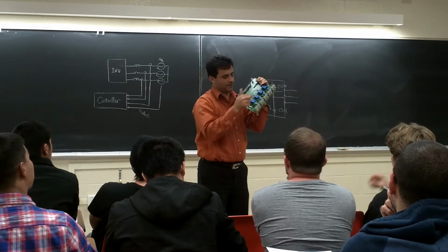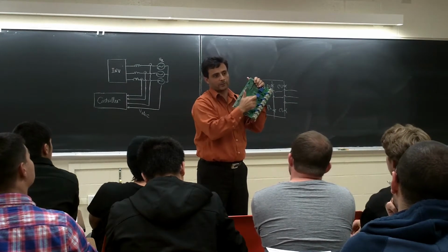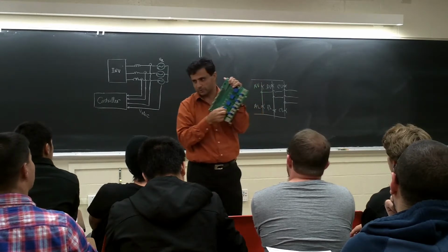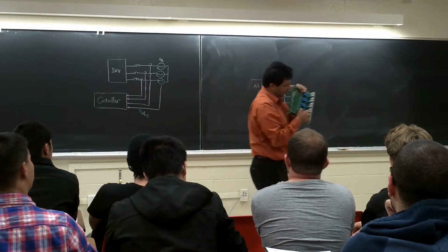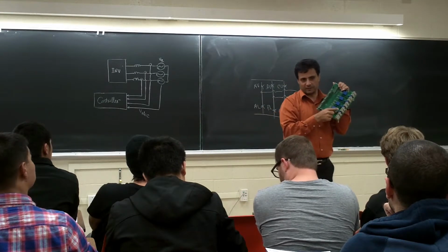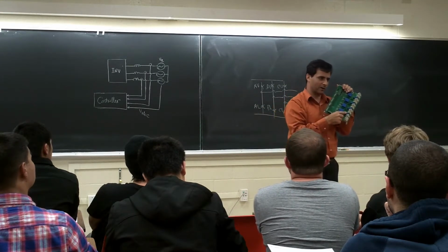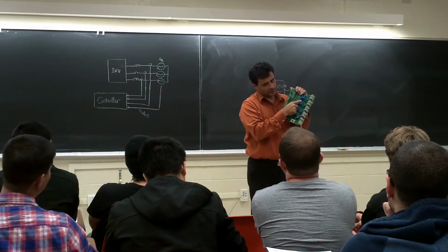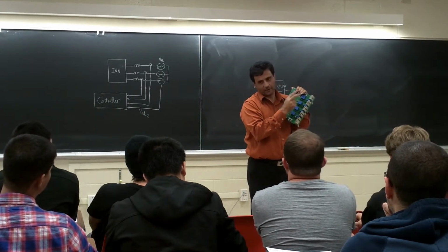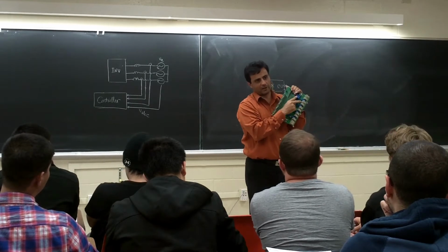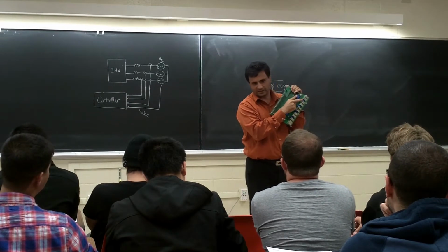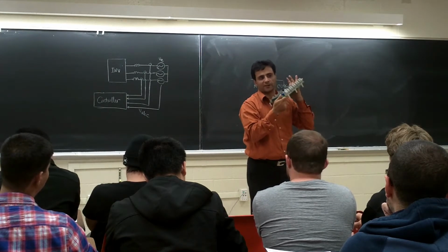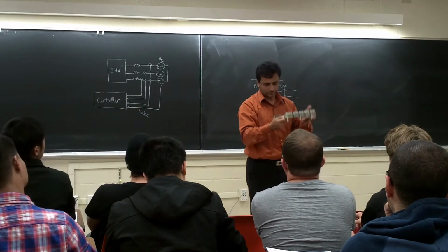Here, the same thing, and these are voltage sensors. These are again expensive. Each of these blue ones is about $40. And this one is about 15, 20 bucks, based on how much current you want. So you measure the 3-phase voltage, you measure the 3-phase current, and just for extra measurement, I measure the DC bus voltage and current, right? So basically, this one doesn't do anything. This is just a measurement board, right?